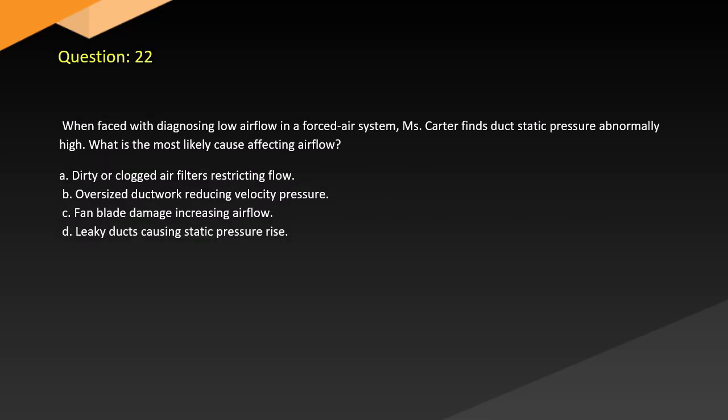Question 22. When faced with diagnosing low airflow in a forced air system, Ms. Carter finds duct static pressure abnormally high. What is the most likely cause affecting airflow? A. Dirty or clogged air filters restricting flow. B. Oversized ductwork reducing velocity pressure. C. Fan blade damage increasing airflow. D. Leaky ducts causing static pressure rise.